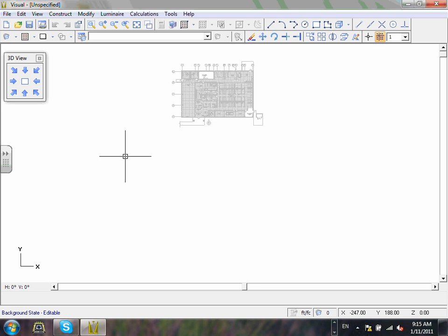Okay? Again, one more time. This button here gets you everything that you need. This is called the background. What we imported, they call it in Revit the background. If you want to make it invisible, you can. If you hit editable, you can move walls and edit it. Almost always, you want to make this one uneditable, so people don't accidentally delete a wall or a ceiling. You don't want to make it invisible. We'll use invisible for other things.